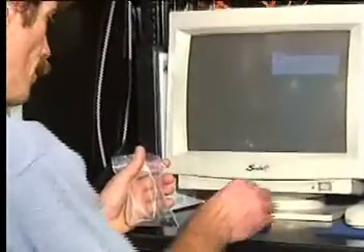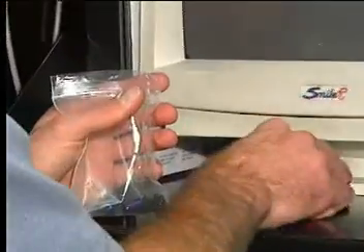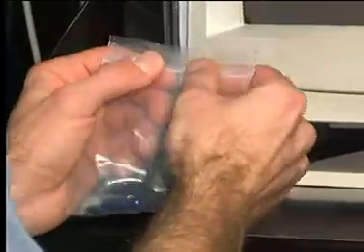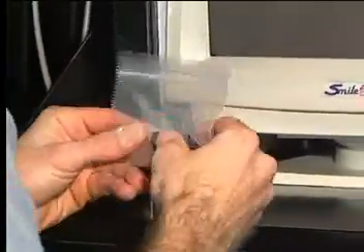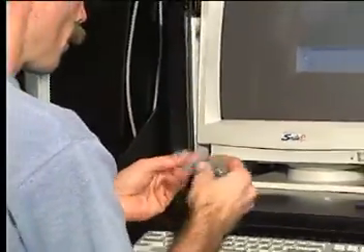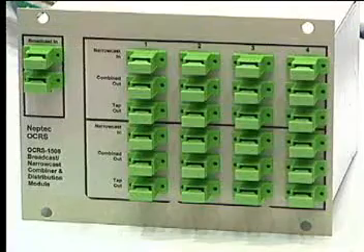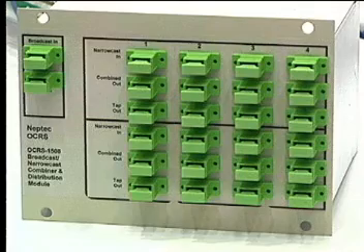Always keep unused connector ports capped, and store unused caps in a small Ziploc bag inside the equipment rack for easy access. The bag will prevent dust from accumulating in the caps and being transferred to the connectors. Remember, however, that all plastic covers contain oils that can outgas and contaminate the connector over time. Covers are most useful in keeping large particles out of the connector.